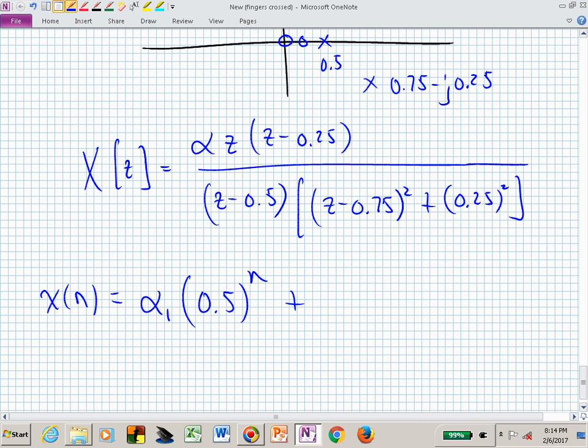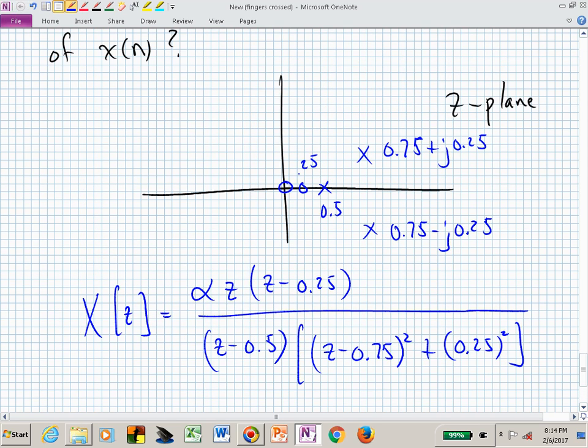When you see complex poles, what should you be thinking? Sinusoids, what kinds of sinusoids? Where are they relative? If they were right on the unit circle, would they be collapsing or expanding? They wouldn't be, would they? They would just be sitting there shaking at the appropriate frequency. But what's this one doing? Where is it located? It's inside the unit circle, so it's collapsing. And it's collapsing now at a particular value. And how do we find the value that it's collapsing?